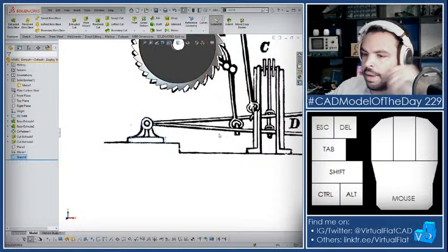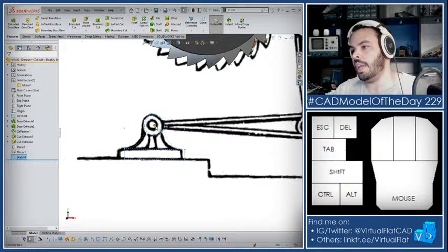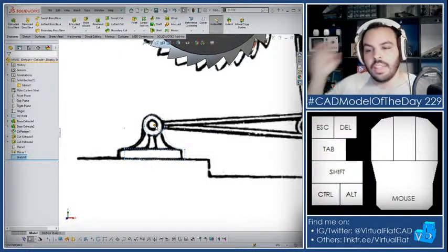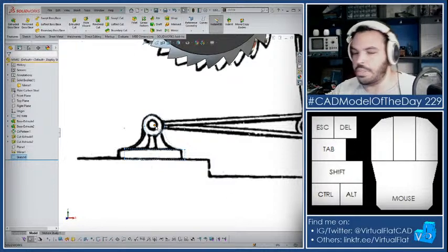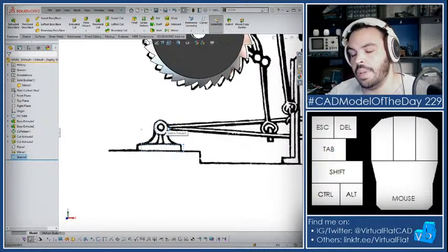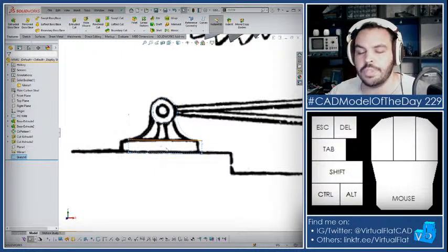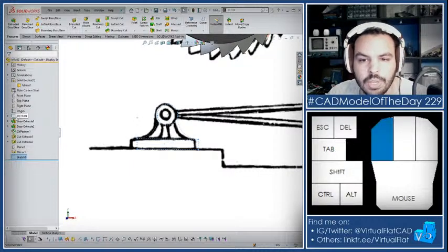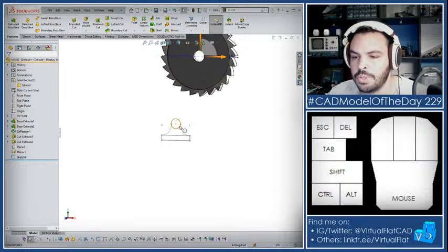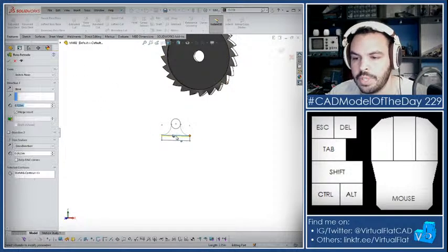even before that, I need to figure out how long this bar is. Again, it's just a 2D sketch, so you don't have that information. You don't have any of those dimensions, and I'm just gonna guess 6 inches. I'm gonna guess that this block that I just sketched out is 3 inches from the plane, and then I'll do a mirror to get the total 6 inches. So let's hide the sketch picture, and yeah, we'll extrude this thing.